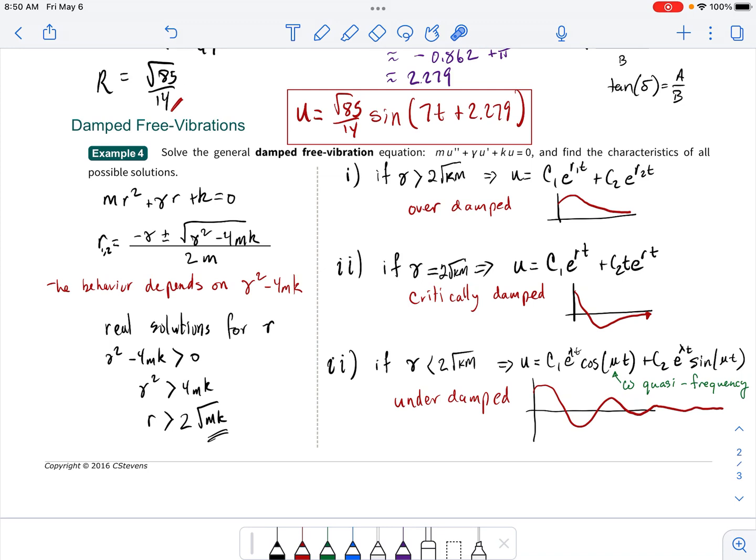And this type of oscillation is called underdamped. It's still damped, but underdamped meaning that it will continue to oscillate until it comes to a rest. That curve is sandwiched between the envelope of our exponential. So you can draw an exponential curve through here, and it's just narrowing down that oscillation until it eventually stops. So there are the characteristics of our unforced